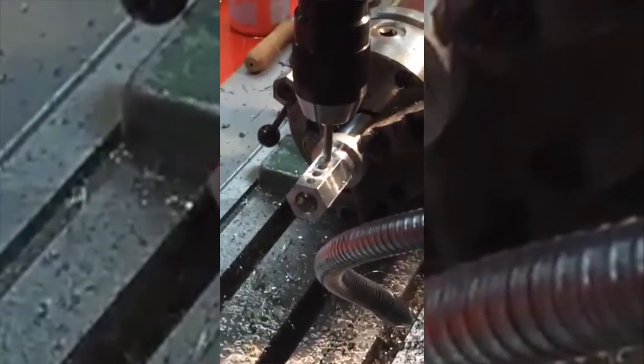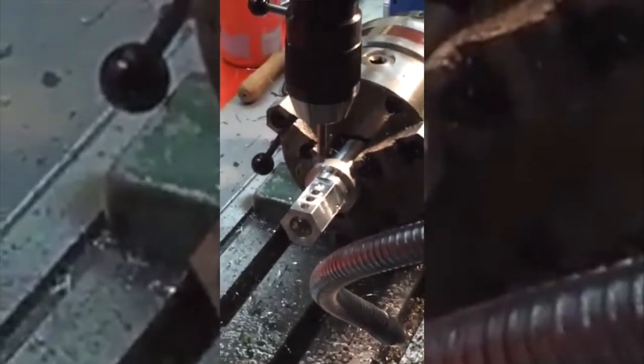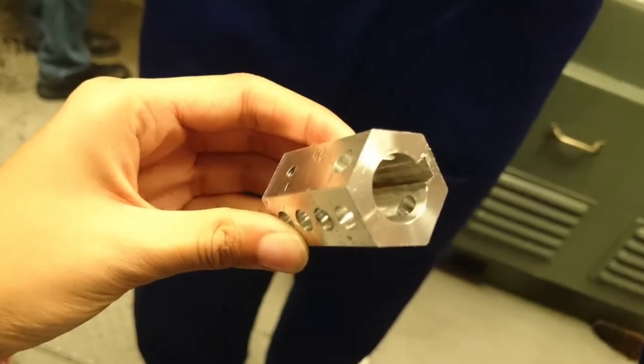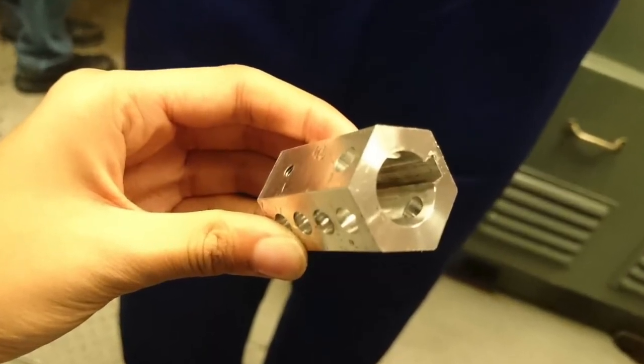Then we used a CNC vertical cutting tool to mill down the edges of the cylinder to form the hexagonal shape. After that, we used the coordinate input in this machine to drill holes onto the corresponding surfaces of the hexagon in order to reduce the weight of our hub and for the grub screws. Finally, we made the keyway by using broaching so that the hub could be mounted in the wind tunnel securely.